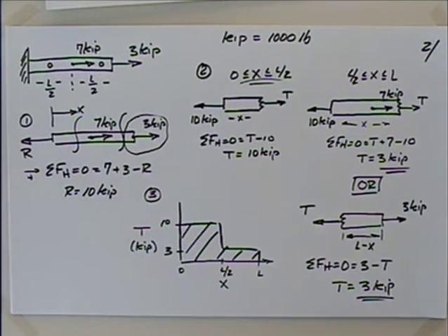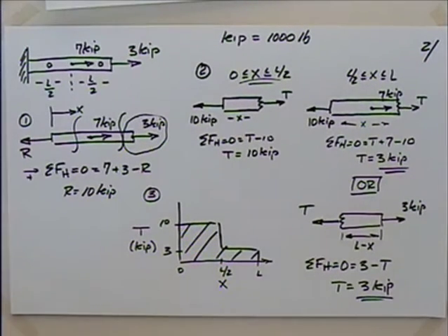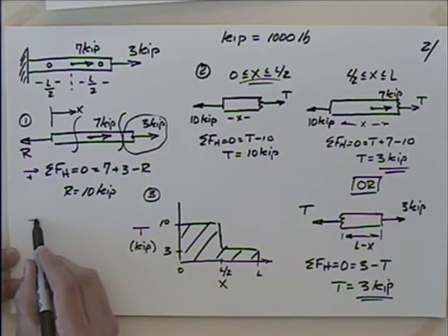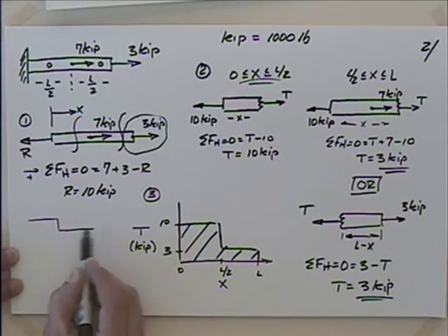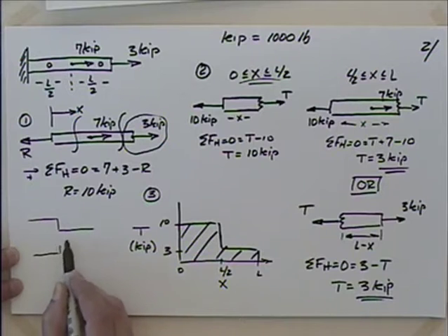The second one, there's a lot less load. Yeah, all things being equal. We'll talk later about stress concentrations and whatnot, something to think about. But just looking at those two pieces, we'd want it on the right-hand side. Or maybe we would want to build this thing like this. We'd want to step this thing down.